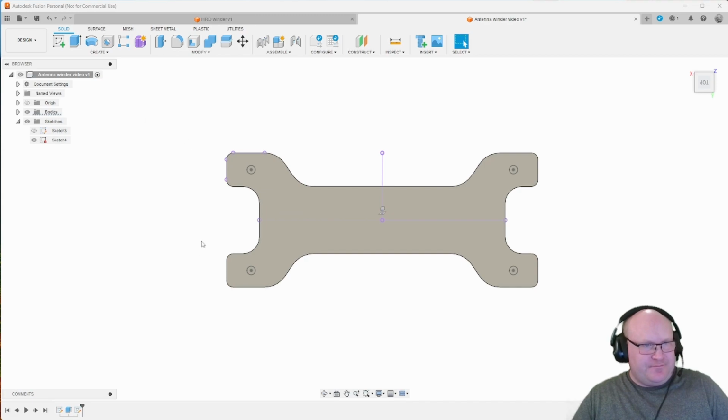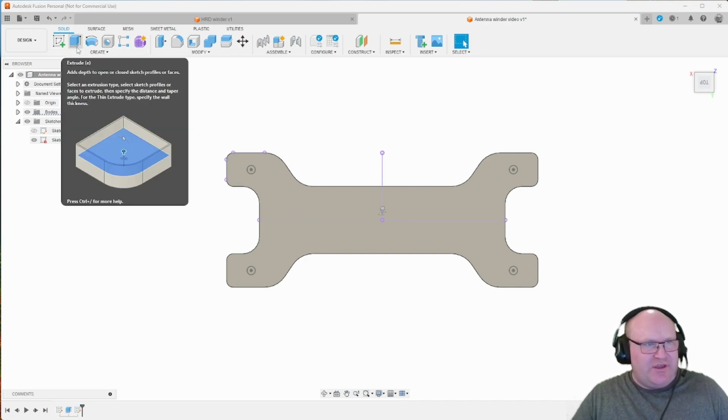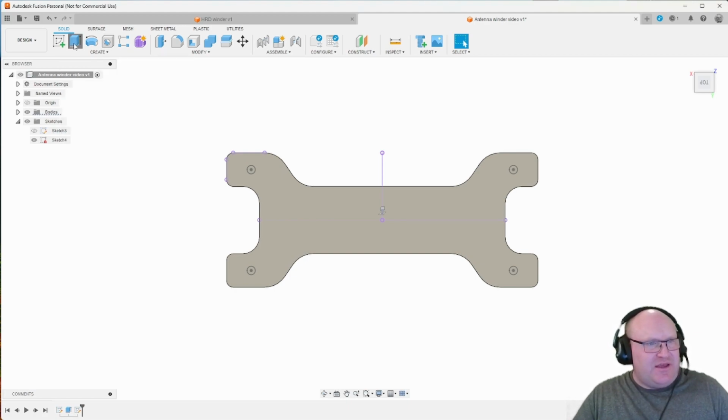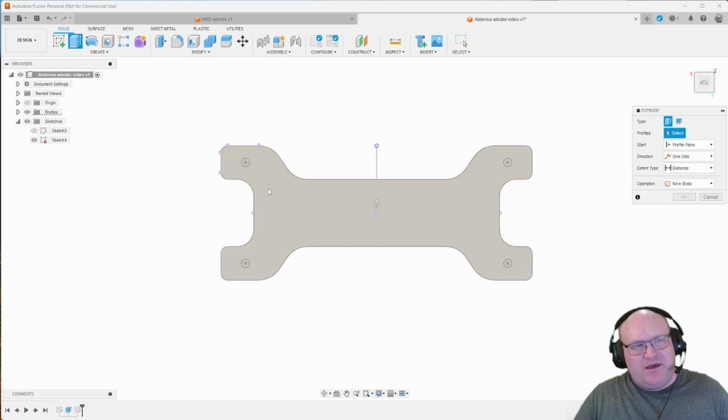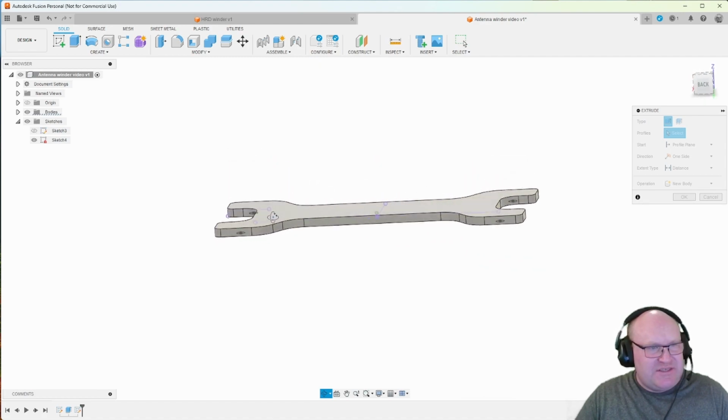Let's show the body again. In here we are going to extrude again. Extrusion can be used either for creating a model, or to cut a hole in one or remove parts of it. So let's click that one. Now I would like to extrude these holes. As you can see, nothing happens when I try to click it because this surface is in the way. This is more visible if I rotate the model, and you can see these ones are on the underside.